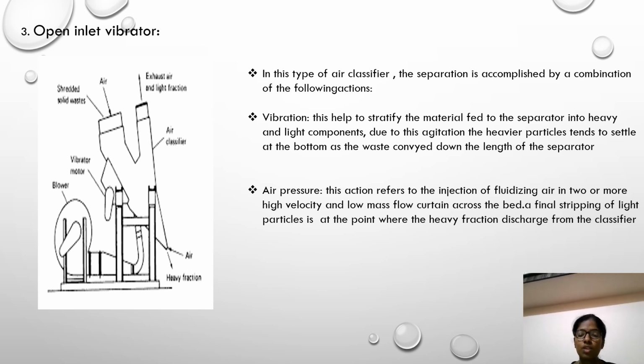Air pressure refers to the injection of fluidizing air at high velocity and low mass flow across the bed, and the final stripping of the light particles is at the point where the heavy fraction is discharged from the classifier.